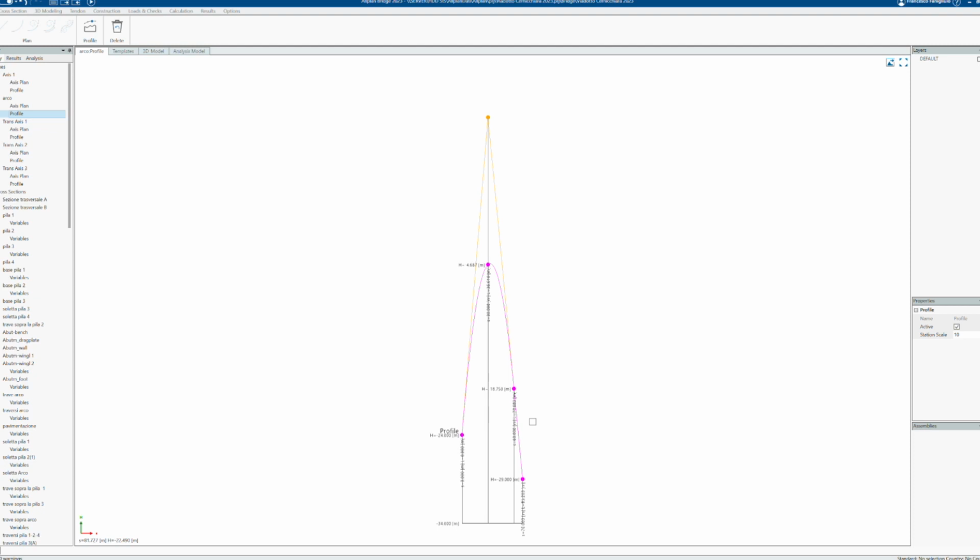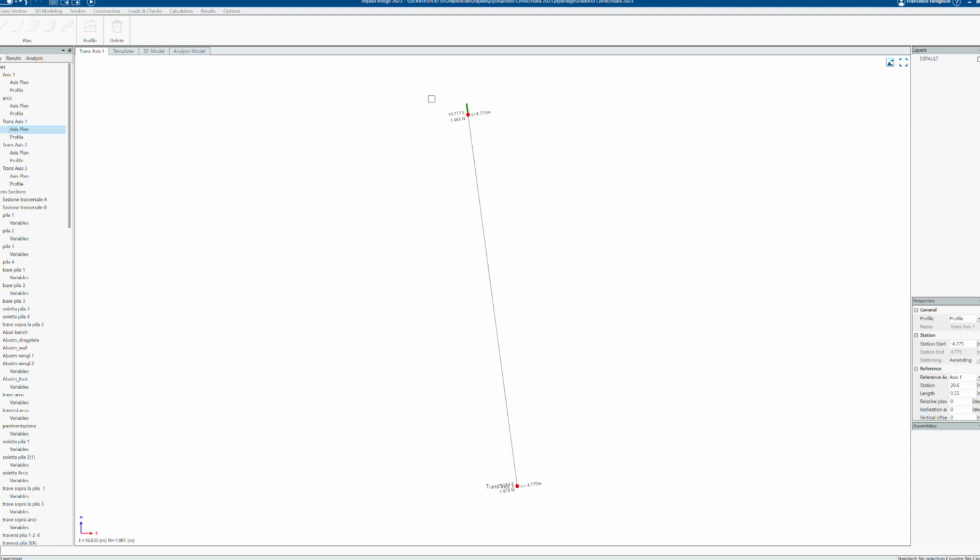However, in Allplan Bridge, as we can see, obtaining the numerical model was quite easy. This way, we were able to obtain the height and both the planimetric and longitudinal developments of the entire viaduct. Other axes, all connected to other secondary elements, were defined in order to realize the model. Subsequently, we defined the cross sections.